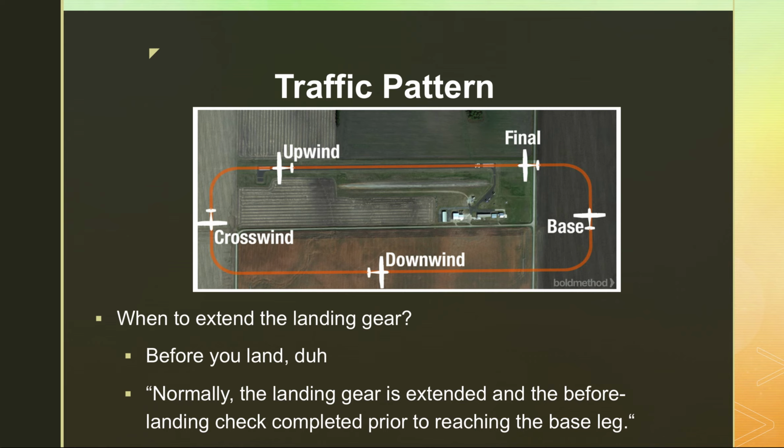So when do you extend the landing gear? Honestly, the best answer is before you land. And I put duh, but different situations require different times. So out of the Airplane Flying Handbook, they say normally the landing gear is extended and the before landing checklist completed prior to reaching the base leg.